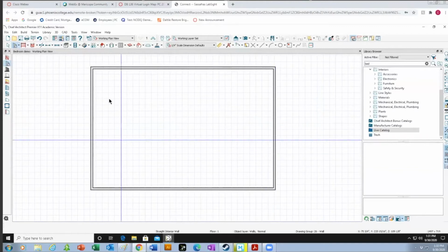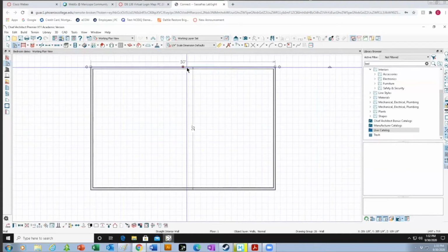We're going to go ahead and edit some of those dimensions just so that you can see what that's like. We're going to click on the upper wall in your building, and we're going to look at that again, and it's 30 feet. Let's see, did I already do all this? I might have done it already. Click on the dimensions, and we want to make a 15-foot by 15-foot room.